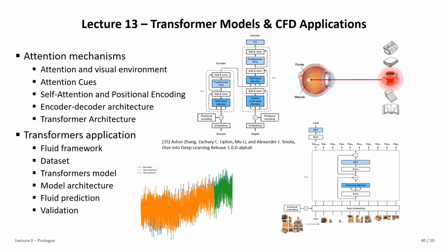We will talk about the transformer architecture and how we can use it for the CFD. Then we will see a practical example for a data set from the turbulent flow. As we said, it's complex and doesn't have a known pattern. So we'll present it practically. We train the model with the data and then make a prediction for the velocity of the turbulent flow, then make a comparison with some other models like LSTM and GRU, which were previously used in our research, and it will present a great validation of this approach.